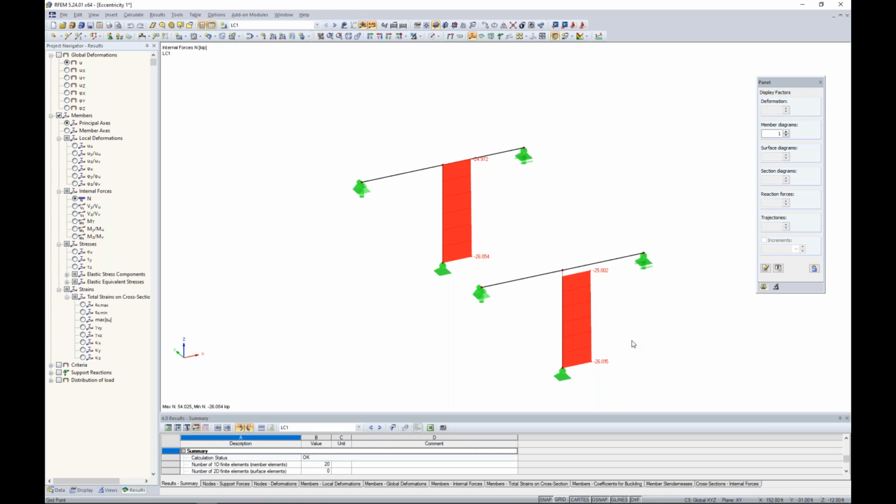So my point being here is that we perhaps have a huge model. We've gone through, we've applied all these eccentricities for our columns to drop that down to the bottom of the beams framing up above it with absolutely no influence or very, very little influence on our results that really doesn't make it worthwhile. So maybe not detrimental here in terms of additional forces, but really no difference. So there's no reason to apply these offsets in these situations.